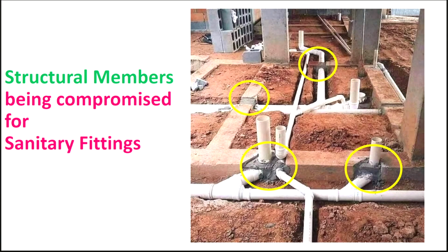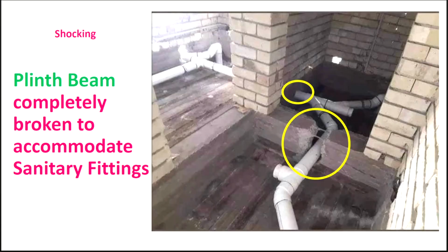Okay, so we are talking about this. Here again they have compromised on the structural integrity of the beams itself. Some more photographs. Now here the entire depth of the beam is gone, the entire pipe has been taken through that, and he is doing his job. Please pay attention. Many times we tend to ignore all these things.